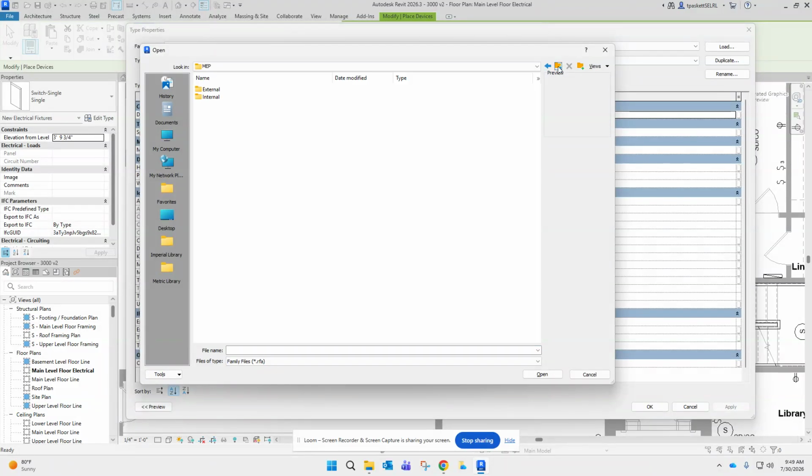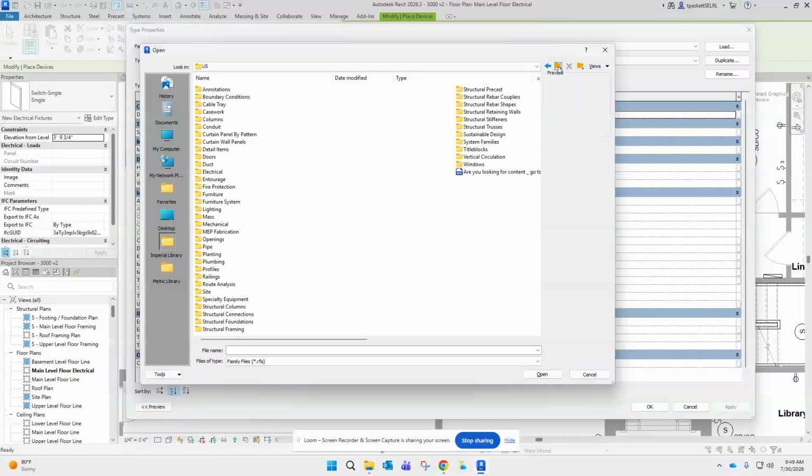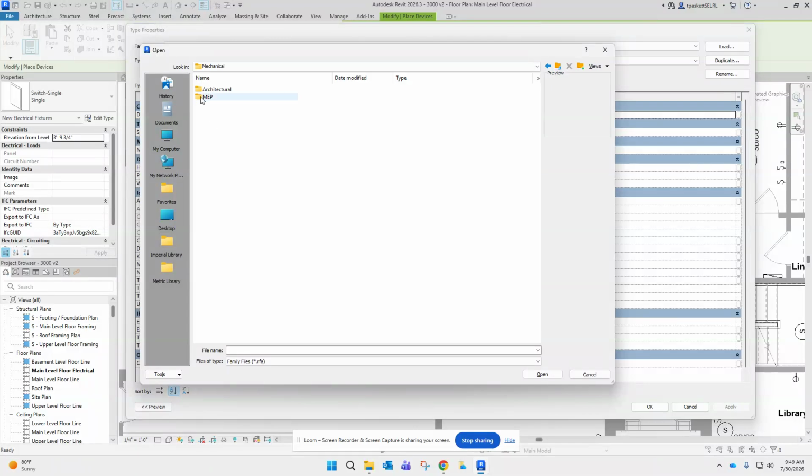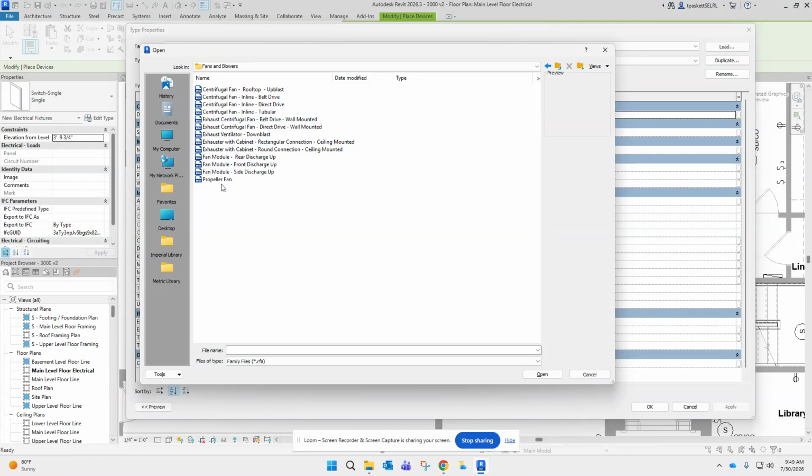I have to go back here, get out of the lighting now. So I mean, it's under mechanical, MEP, air components. So then move air, and we want, nope, I missed it. Nope, there it is, fans and blowers. Open up fans and blowers. And I just want a simple little exhaust fan. Make sure it's exhaust that you're getting in there. You're trying to pull the bad stuff out.